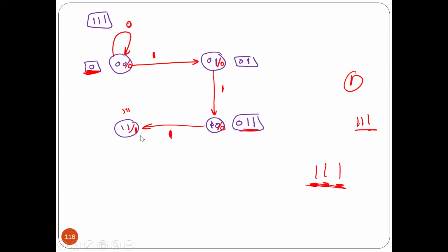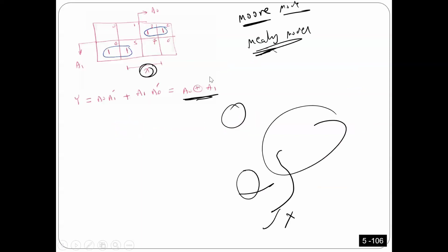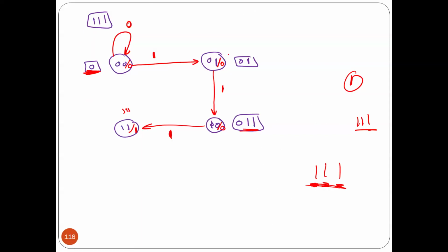I already received it. Okay? As you know, in this state diagram, I have to consider the 2 cases for each state, if the input is 1 or 0. So let's think about it. If I'm here, that means I received 0, 1. If I receive 1, I'm gonna proceed to the next state here. What if after 0, 1 you got 0? What should I do? You have to move back to here.